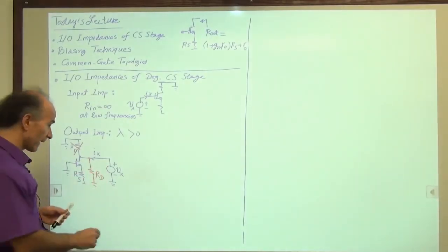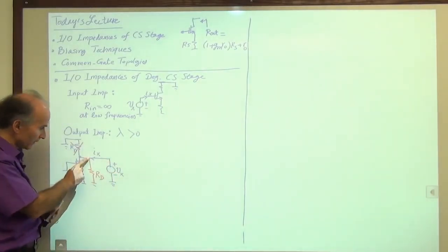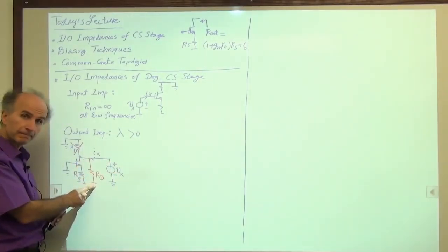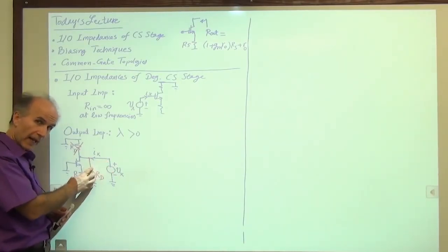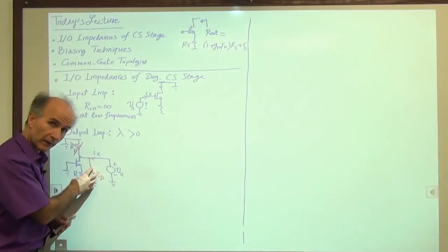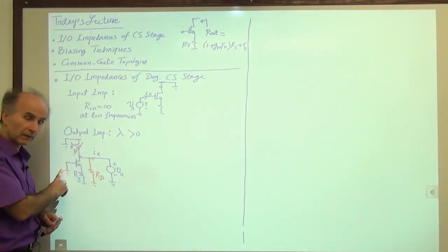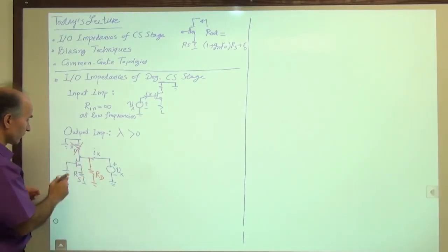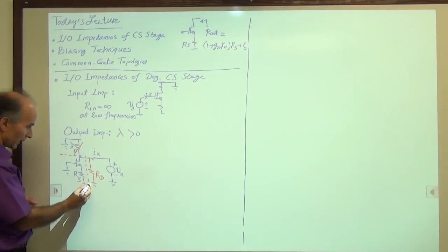All right, so what we see is that this voltage source sees a resistance from here to ground. Okay, so the voltage source sees at least this RD, and then in parallel with this RD, it sees some other stuff. Why in parallel? Because this other stuff can go into a box with two terminals, like so.